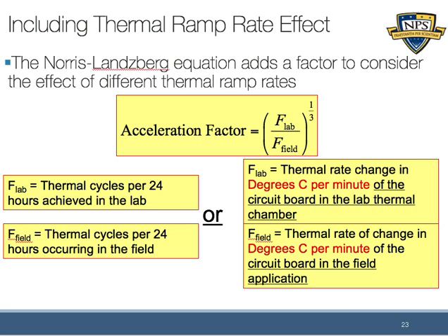And it uses 24 hours because most commonly the low cycle fatigue type of failure mechanisms are the result of diurnal cycles, meaning that they're subjected to daily temperature swings, and so just naturally the Norris-Landsberg model is kind of normalized to that value. But it doesn't really matter, right? You could say that one temperature swing in the field is 4 hours, okay? Use the number of cycles in 4 hours would be 1.